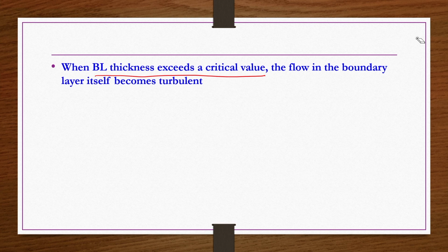So, this transition from laminar to turbulent boundary layer occurs at Rex approximately 10 power 5. So, that is if the fluid is Newtonian. Okay. For a Newtonian fluid, rho V naught xc divided by mu is approximately 10 power 5. So, if you have to find out the xc value up to which the boundary layer is laminar, you have to use this one. So, what you understand from here is that this xc value is dependent not only on the free stream velocity, but also on the density and the viscosity of the fluid.